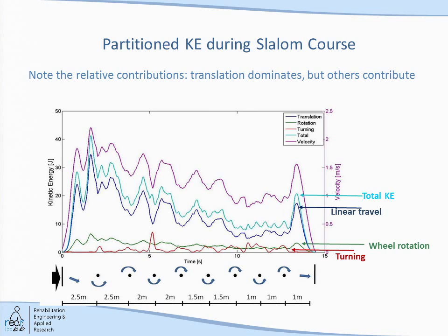The weird thing about turning, again, what makes wheelchairs inefficient, is you're accelerating one side of your chair while you're slowing down the other, okay? That's another thing that makes propelling a wheelchair highly inefficient, but it's something we don't study when we don't turn. If you're going to study maneuverability, you have to take this inefficiency into account, where you're applying torque on one side and slowing it down on the other. That's why it's so jagged, because you're propelling and braking at the same time to maneuver. Okay, that's effortful. It requires effort to do that.